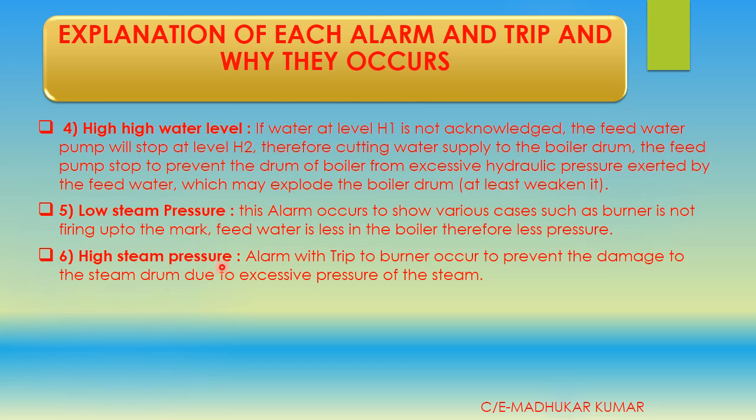For high steam pressure, you have the alarm and trip. The burner will stop, and it prevents damage to the steam drum due to excessive pressure of the steam. So in this case you have the high steam pressure alarm as well as trip.